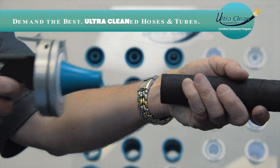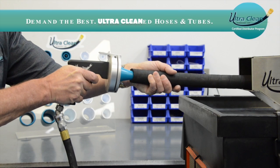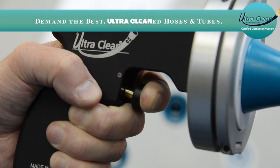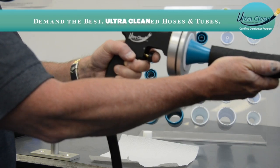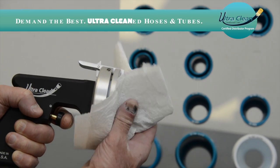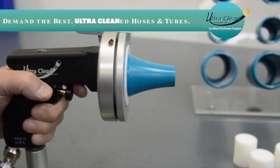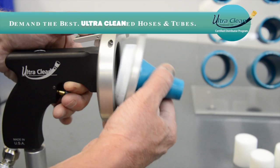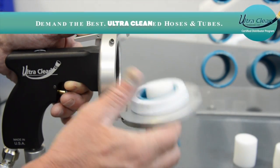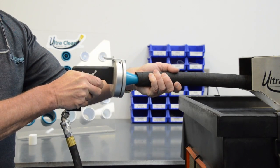Insert the nozzle into the hose. Secure the other end of the hose into the containment barrel or catcher bucket. Depress the trigger until the projectile has exited the opposite end of the hose. Wipe the end of the nozzle clean and repeat this process now through the other end of the hose. The ultra-clean projectile strips out the internal contamination as it travels through the hose and around bends, forcing the contamination out in front of it.